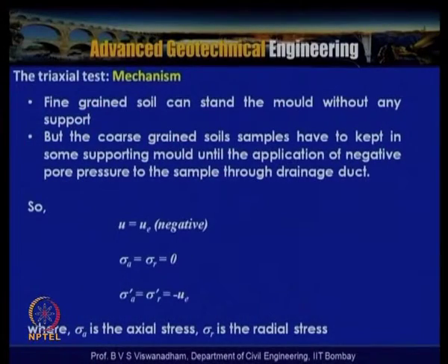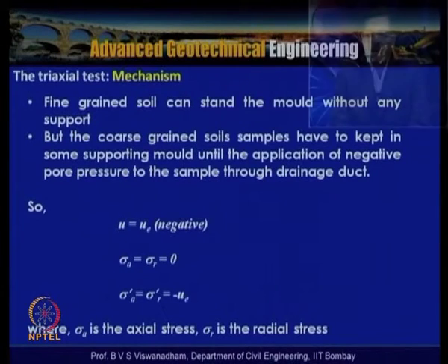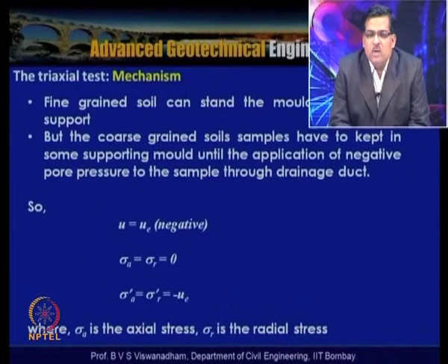Fine grained soil can stand in the mold without any support, but coarse grained soil samples have to be kept in some supporting mold until negative pore water pressure is applied to the sample through the drainage duct. Fine grained soil samples can support themselves, but coarse grained or sandy soil samples have to be kept under some suction, and afterwards the suction is released gradually.